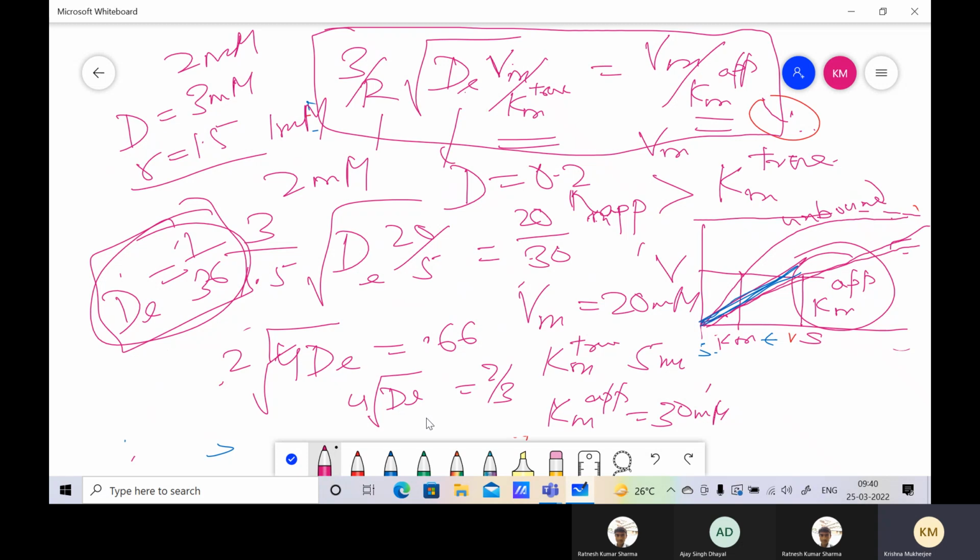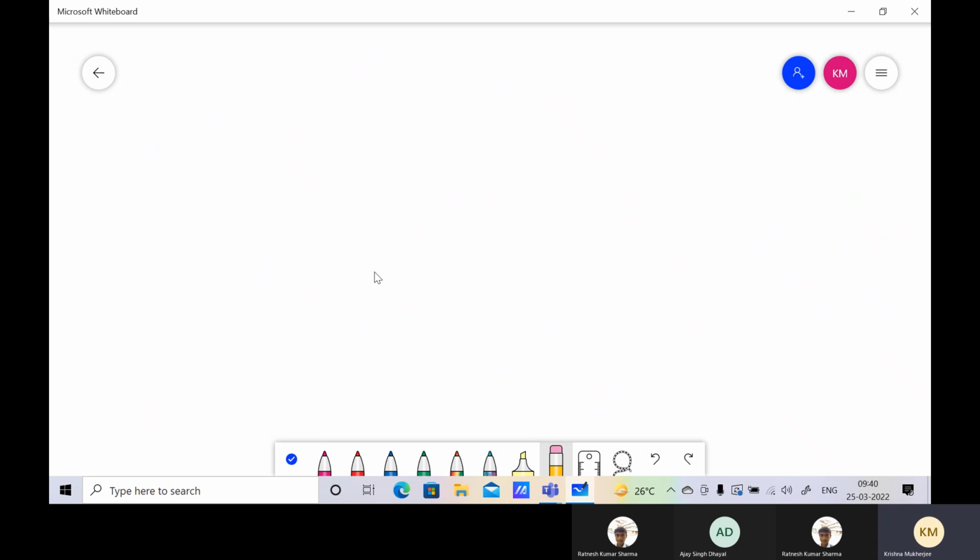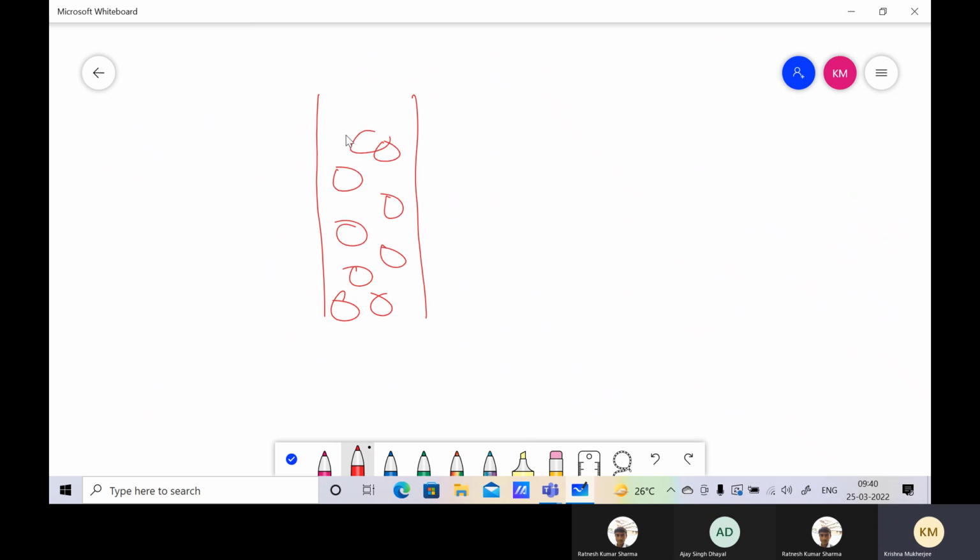Yeah. And of course, let us not get into more complicated stuff, but I suppose you can understand that I can now say that I have found out this as well as this. So I will now pack them in a column. And so there are two mass transfers operating, the external and the internal. And then I will try to find out the phi values at different parts of the column, and they will be changing. That is a serious issue here. And then I can find out the Biot number, which is phi tan phi.